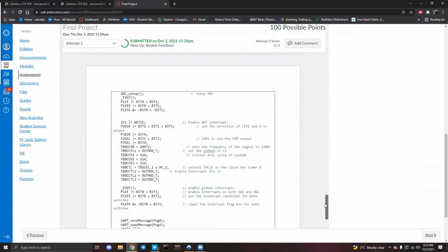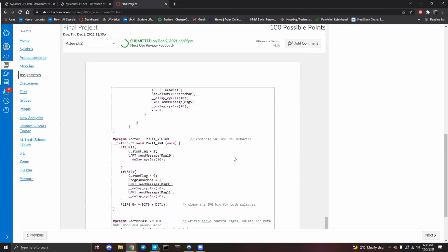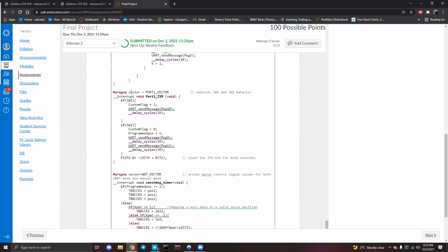So this is basically treat those switch 1 and switch 2 calls as testing if the flag is pending. So you go in, you test if switch 1, move in here, do your thing, hit a reti. This is C, so it's a little different, but what essentially happens is I could press switch 1 and switch 2 at the same time, and it would enter either way. Regardless of the order I press, switch 1 or switch 2, it goes into this port 1 vector.